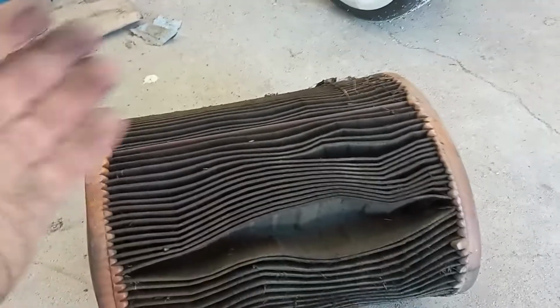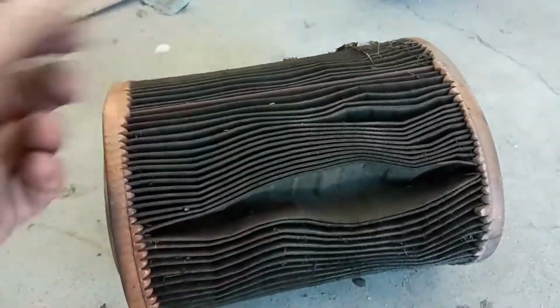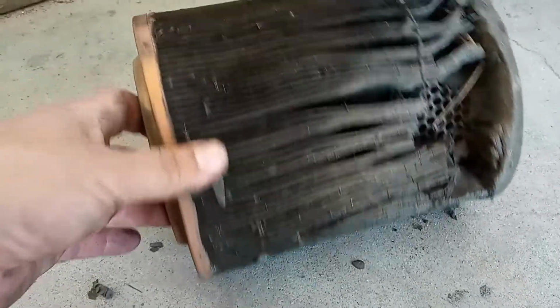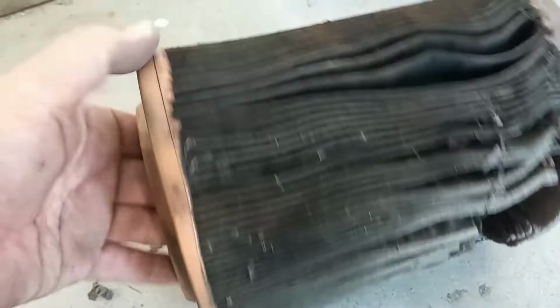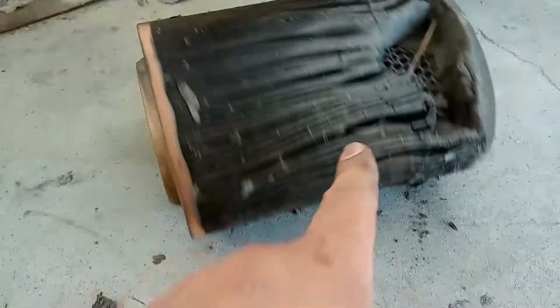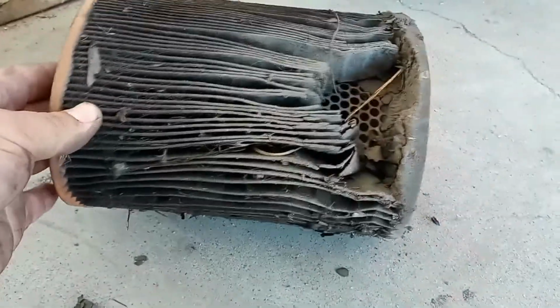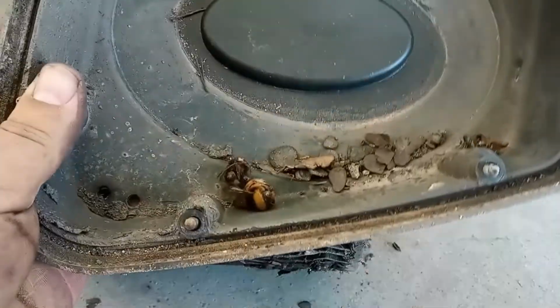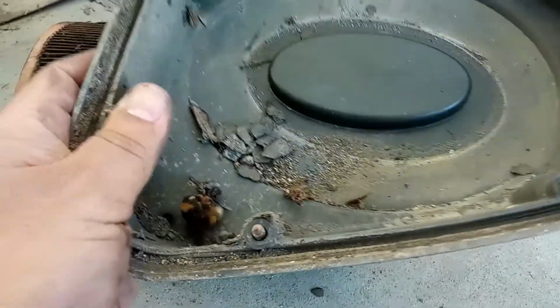If you start to see that the engine is starting to consume oil, it is because the piston rings and the piston ring area of the piston is gone. Dirt will eat out your piston rings like crazy. It is like sandpaper. So let's clean everything out. The cover is all with the bumblebees and dirt, and try to see if I can save this engine.